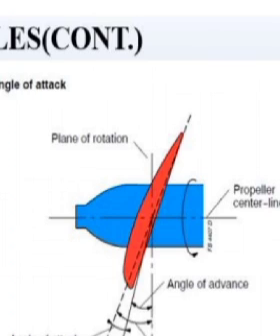So we will need to increase that angle. By increasing the angle, you introduce what we call the angle of attack, which means you tilt the propeller blade in such a way that it makes an angle with the incoming airflow. Now somebody will ask, how is the blade tilted? The blade is tilted manually, or it can be tilted automatically, which we will talk about in our next lesson or subsequent lessons.